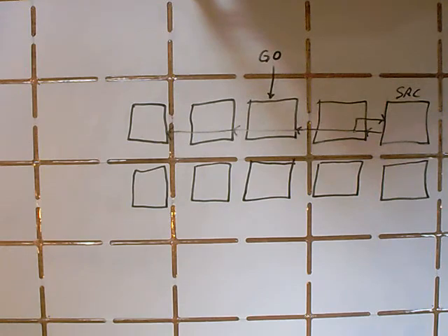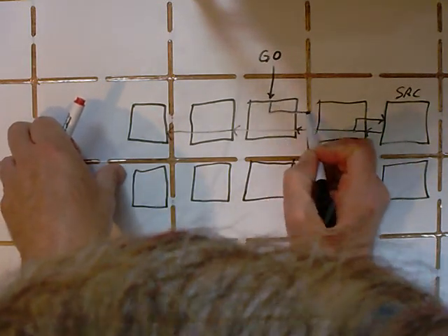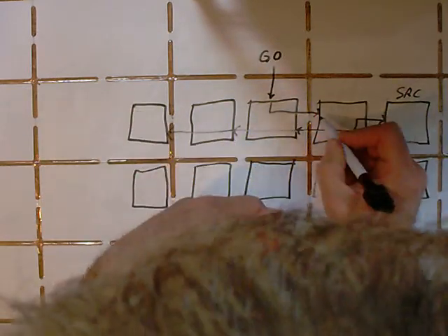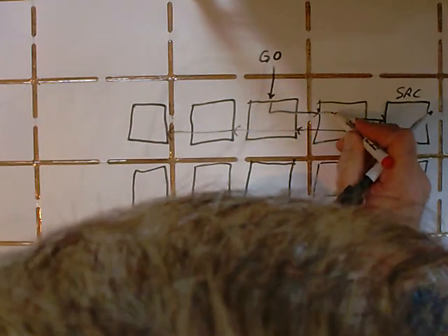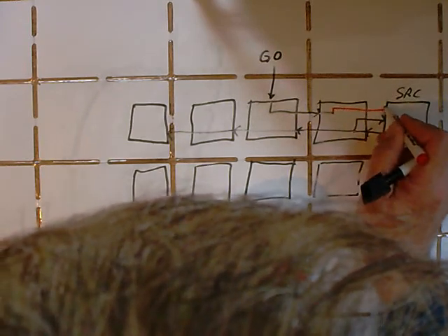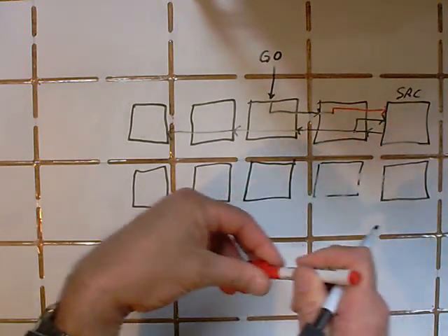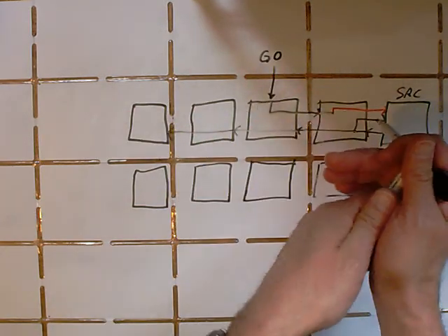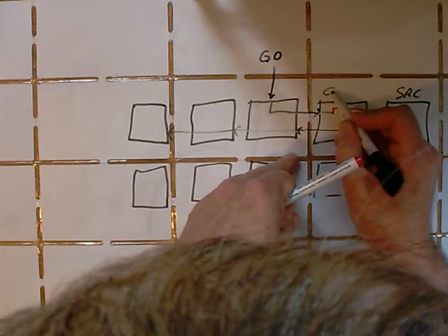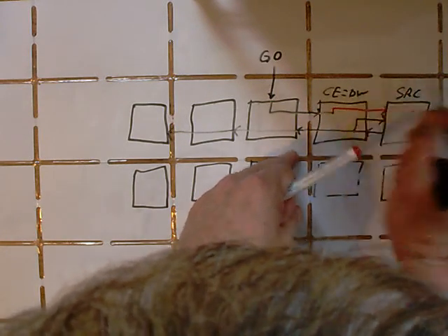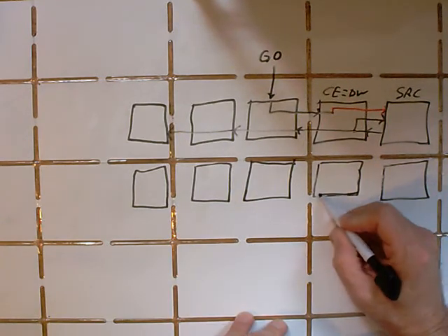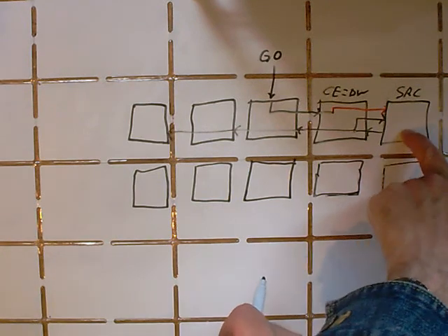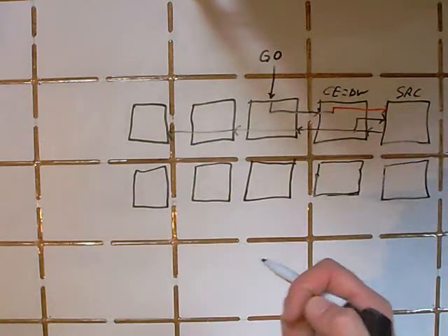So I'm going to use my go signal to do a few things. One, I'm going to send it over into this cell's D input. But here I'm going to take that D input and transfer it to the C output and send that into the C input of the source cell. So the truth table in this cell would be something like control east output equals the data west input. So now if I set the go line to 1, this cell goes into C mode. If I leave go at 0, this cell is operating in D mode.